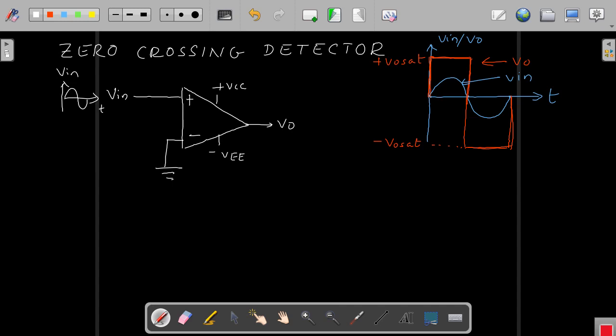So whenever the input is above the differential voltage, so if I take the previous example, say 300 microvolt, if you assume that I have taken a similar operational amplifier with the characteristics which I have shown in the previous slide, then whenever the input goes above 300 microvolt from initial minus V0 sat, the output will now swing to plus V0 sat, and as long as your input is greater than plus 300 microvolt or VID differential voltage, the output will remain in plus V0 sat only.